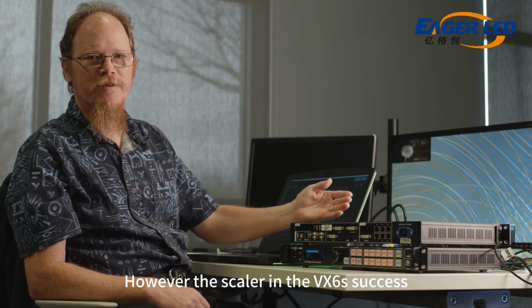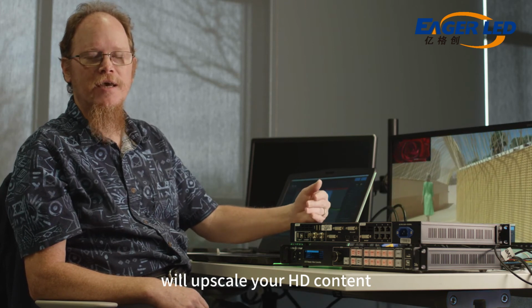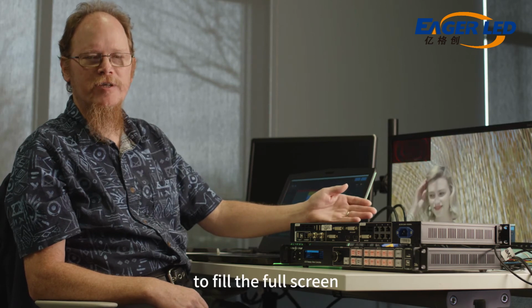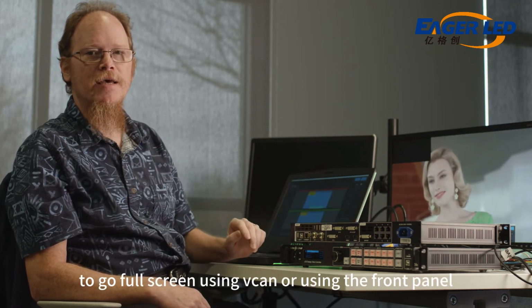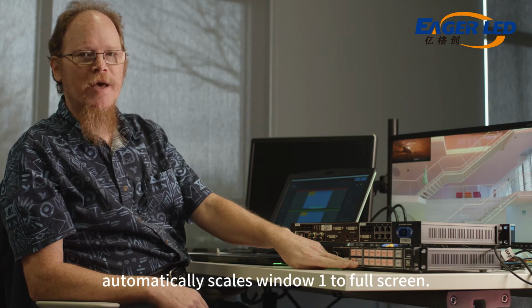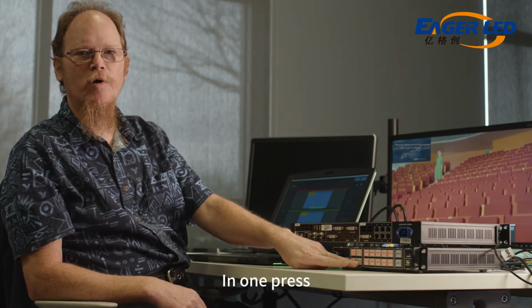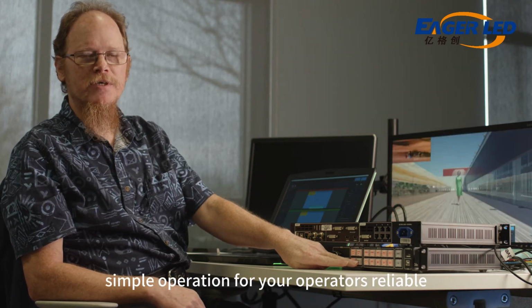However, the scaler in the VX6S will upscale your HD content, either 3G SDI, HDMI, or DVI, to fill the full screen. To go full screen using VCAN or using the front panel, a single button press on the scale button automatically scales window 1 to full screen in one press. Simple operation for your operators.